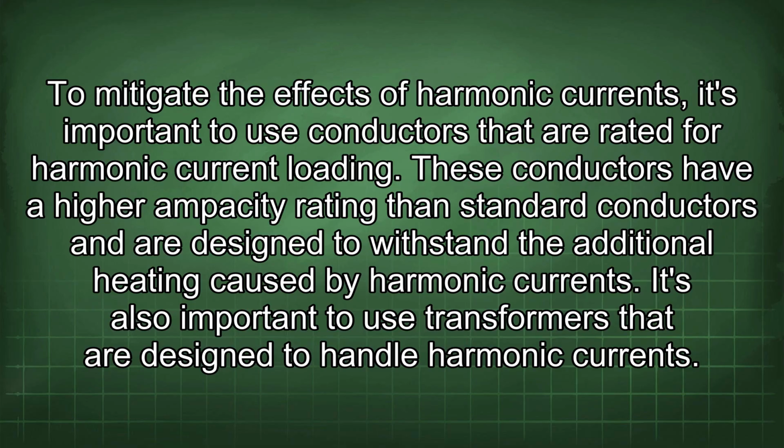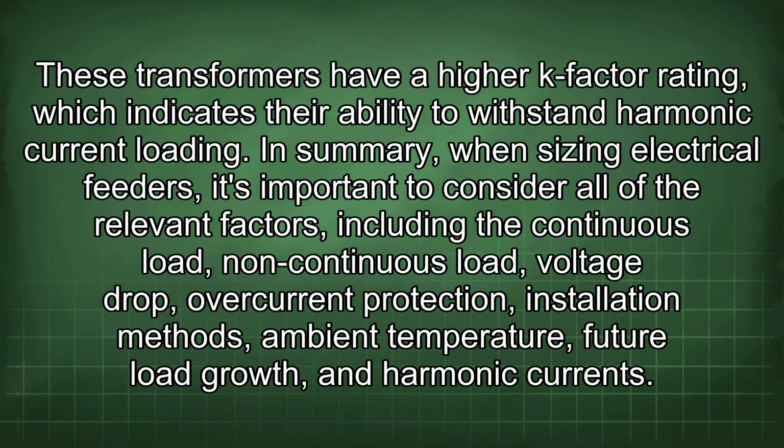These conductors have a higher ampacity rating than standard conductors and are designed to withstand the additional heating caused by harmonic currents. It's also important to use transformers that are designed to handle harmonic currents. These transformers have a higher K-factor rating, which indicates their ability to withstand harmonic current loading.